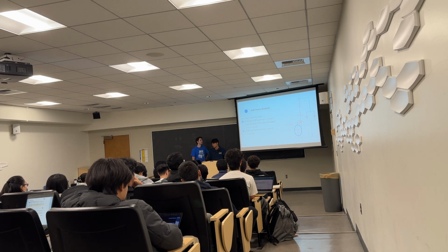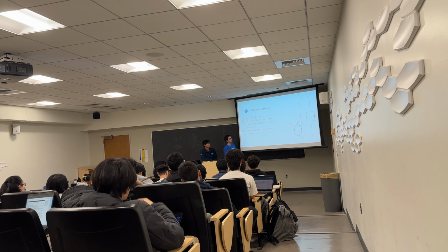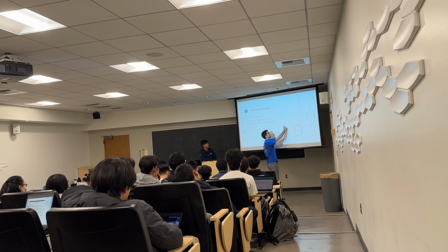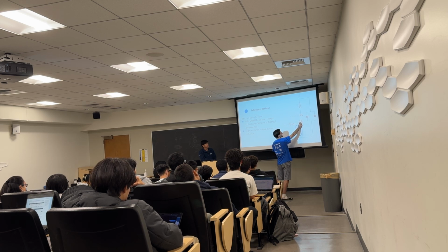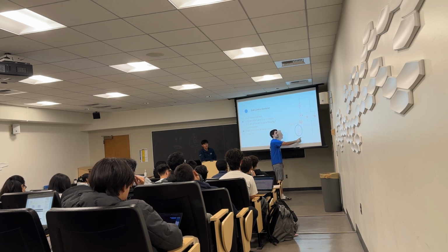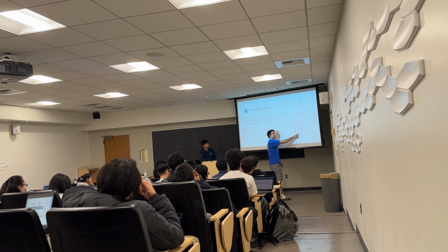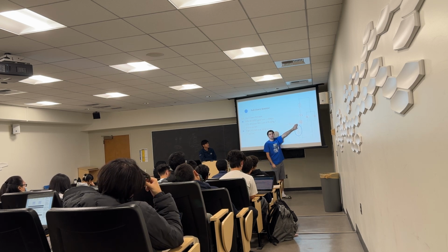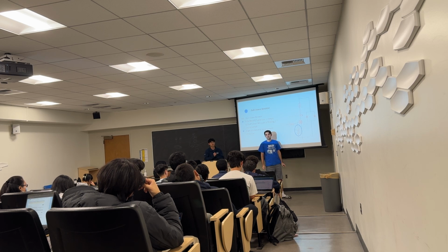So I'm just gonna walk over here. When there's current flowing through here to try to get through to the pin, it also wants to flow through here, but because of the extremely high resistance, a lot less of the current is going to flow down through here. If this was a lot lower value, the current would have a lot easier of a time flowing down through here, and we don't want that. We want most of the current to go through here. If you know V equals IR, you know why that makes sense.